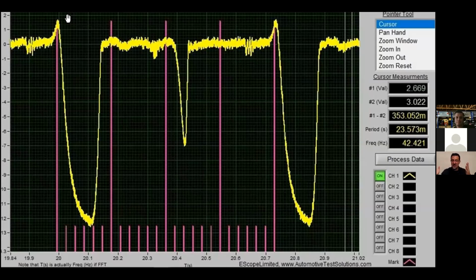So now it hits me like a ton of bricks. I said, holy smoke. I don't have low compression because I've got this huge hole in this combustion chamber. I have low compression because my intake valve is extremely late, at least on this cylinder, right? It's supposed to close over here, and it's closing way over here.